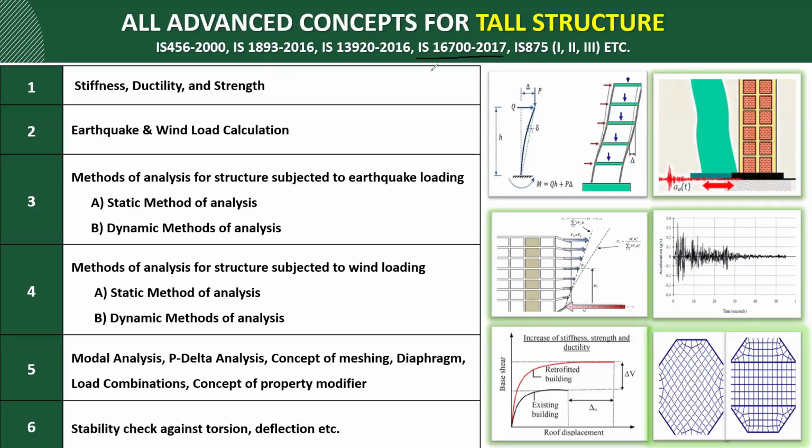This is the code for the tall structure, for the high-rise structure. This code specially recommends considering the property modifier concept, the stiffness modifier concept. It is recommended to implement it in your design model, in your proposed structure, so we are going to consider it in our training for our proposed structure.